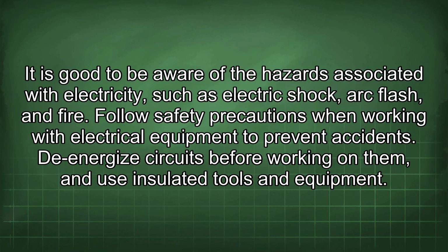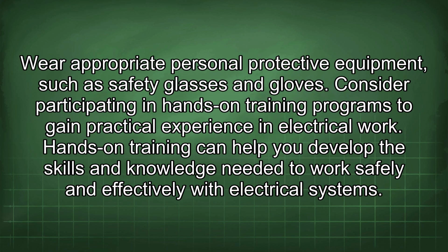It is good to be aware of the hazards associated with electricity, such as electric shock, arc flash, and fire. Follow safety precautions when working with electrical equipment to prevent accidents. De-energize circuits before working on them and use insulated tools and equipment. Wear appropriate personal protective equipment, such as safety glasses and gloves.